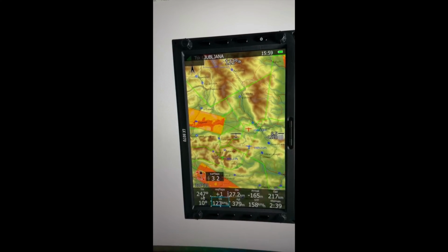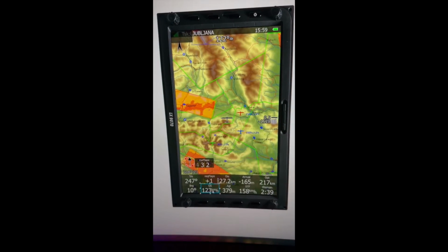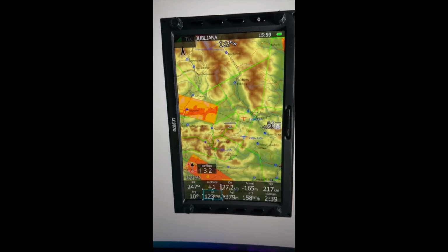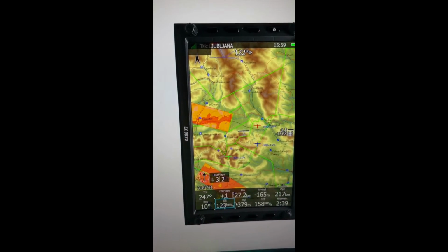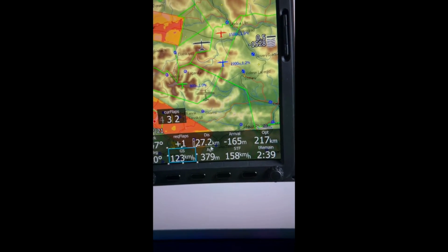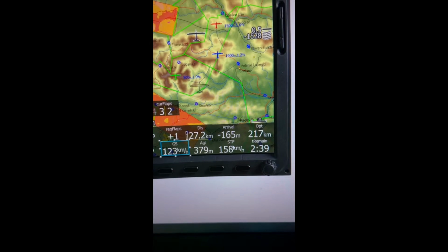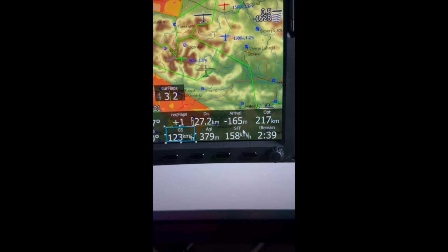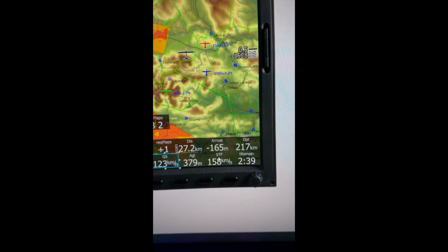Over here you see the track, and the heading to the next turn point. Over there you have the ground speed. You really need this, to not get penalty points. And in Marburg Open we have set it up to 250 kilometers ground speed. So this is the indicator you need to use. What's also important is your distance to target, also your arrival, and this is the speed to fly. So if you're heading to a turn point, it shows you the speed you have to fly. And of course there's the time remaining over there.